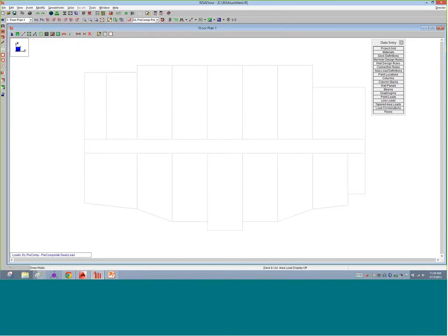So when I'm drawing walls, I'm just going to be drawing it around there. Let's see, this is rendered. I'm going to just turn it. You'll notice when I draw these walls, they are red. Red versus blue indicates that they're lateral walls. And I'm just drawing these around the perimeter of my building.